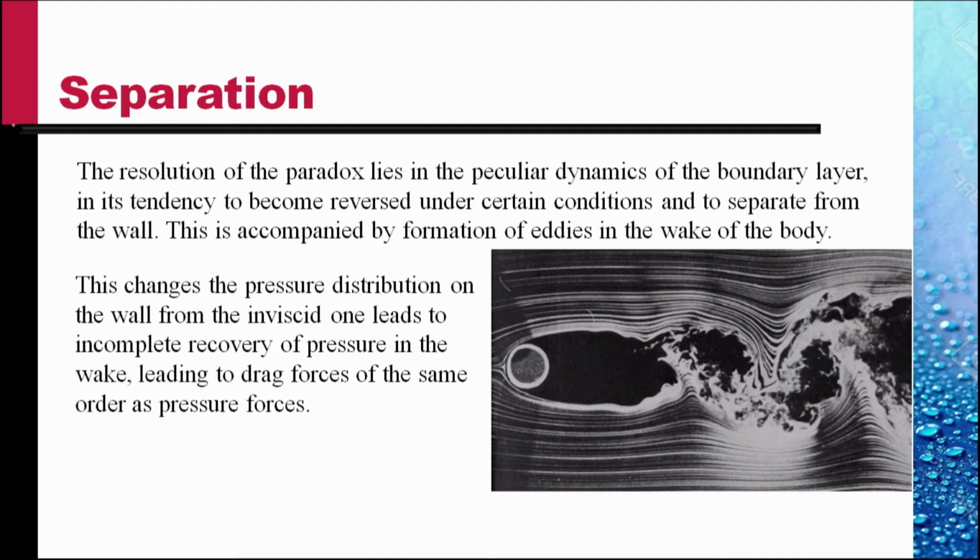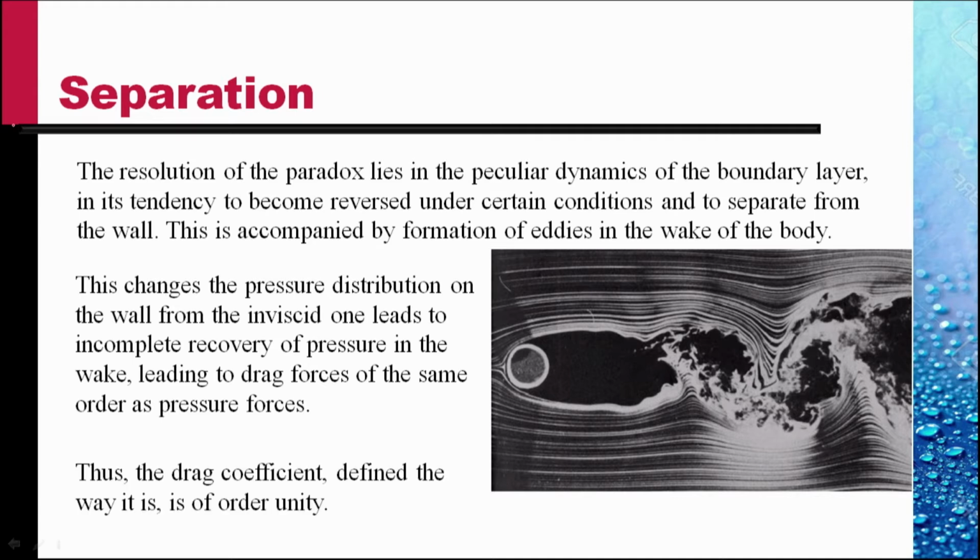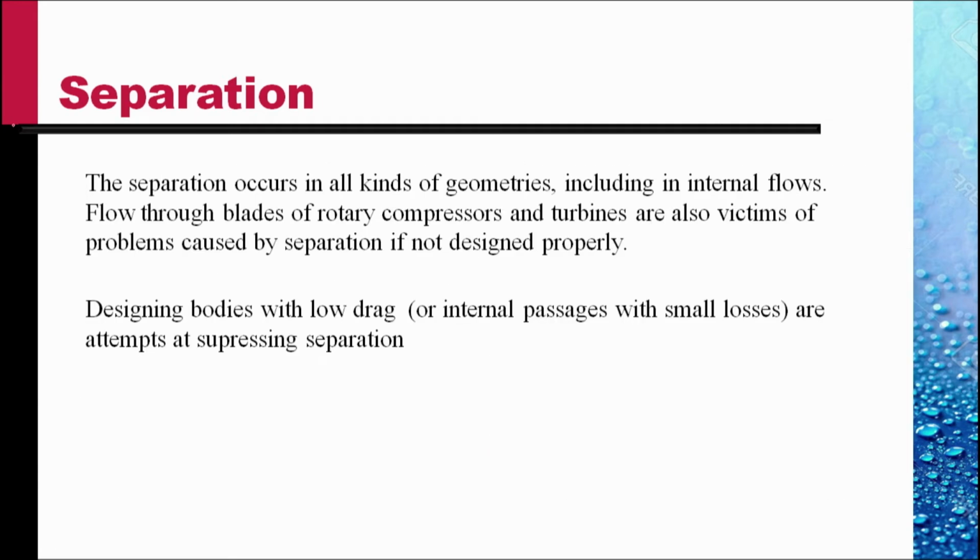And the pressure drag is of order 1. Thus, the drag coefficient defined the way it is, is of order 1. The separation occurs in all kinds of geometries, including internal flows. Flow through blades of rotary compressors and turbines are also victim of the problems caused by separation if not designed properly. Designing bodies with low drag or internal passages with small losses are attempts at suppressing separation.